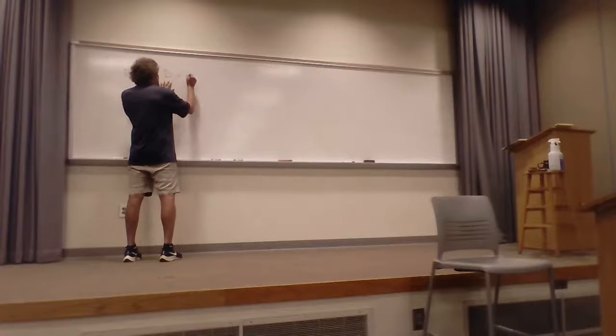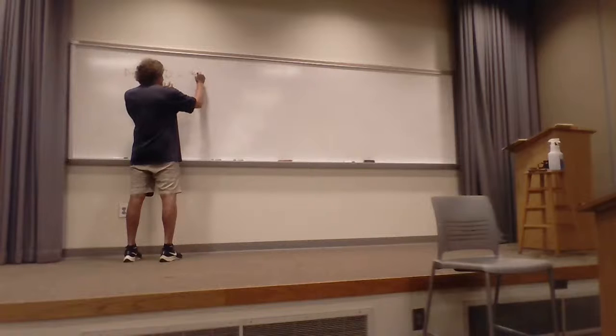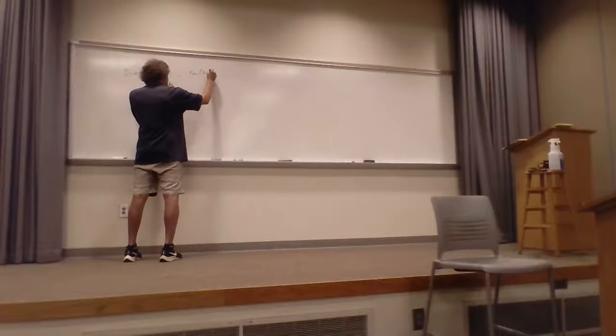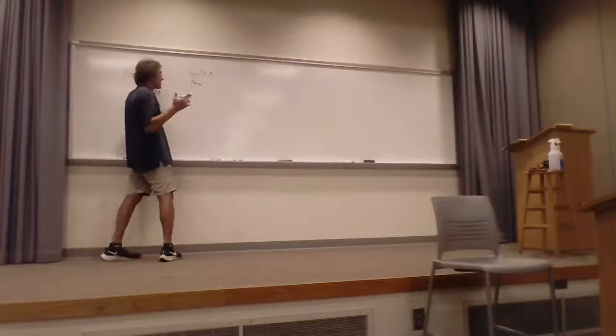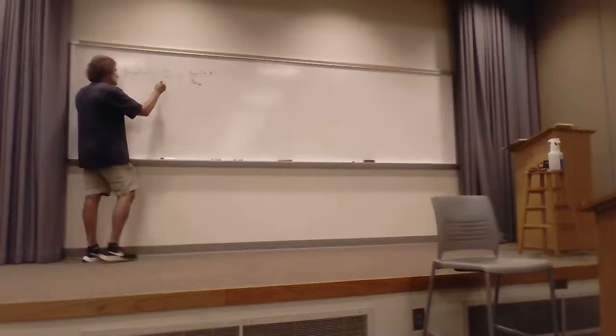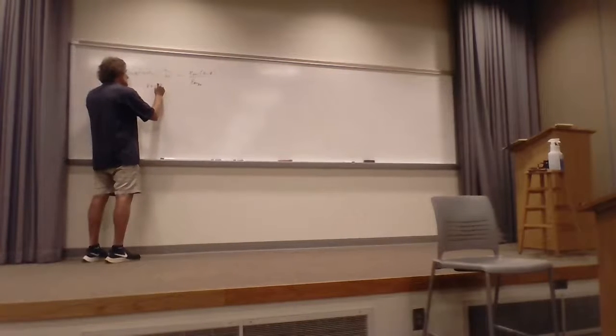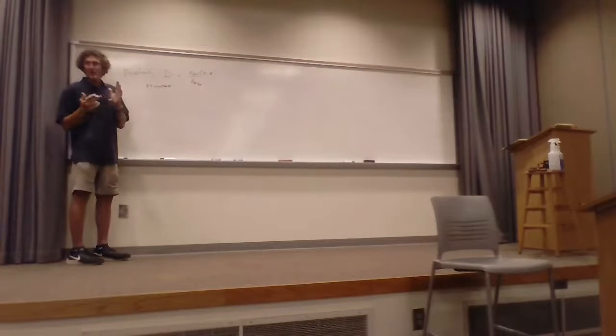And what is it? Well, the directivity is equal to the actual power density, P_AV, that your antenna has as a function of phi and theta, versus what an isotropic antenna would have. So I'm going to just say this, hold R constant for this one, so R is a constant. Well, I'll try to make this more real.